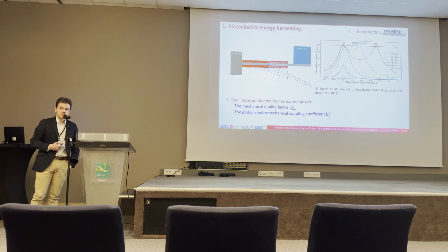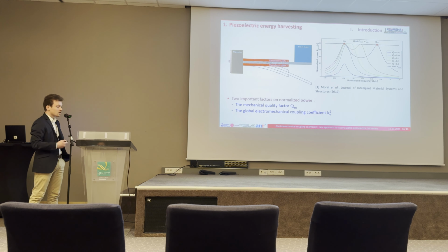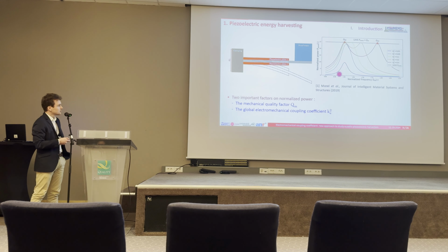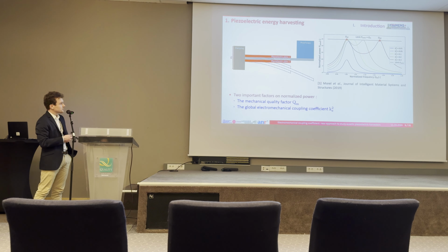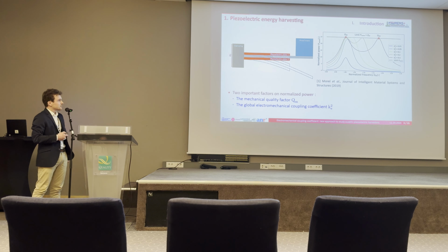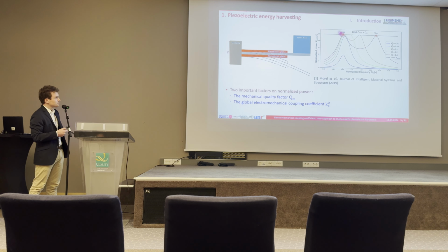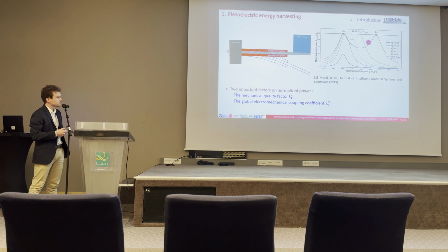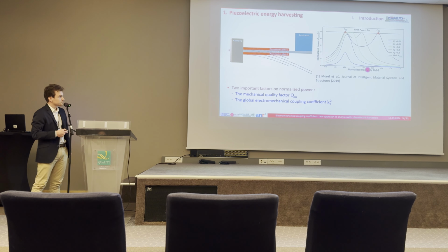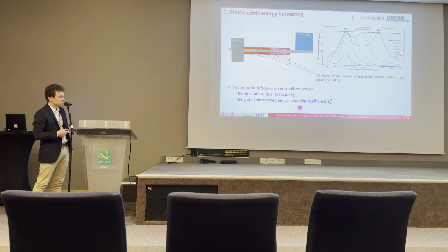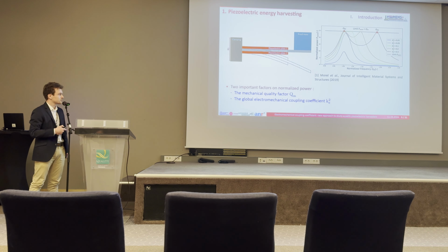We work on piezoelectric energy harvesting, and especially on increasing the coupling coefficient of the harvesters. Here on the right, you can see for purely resistive load, which is optimal, the normalized power to the normalized frequency. And you can see that by increasing the coupling coefficient, you also increase the maximum power, the limit power, which is given up to the mechanical quality factor. So this is quite a good graph to explain our work, because it explains the two very important factors here, the mechanical quality factor and the coupling coefficient.